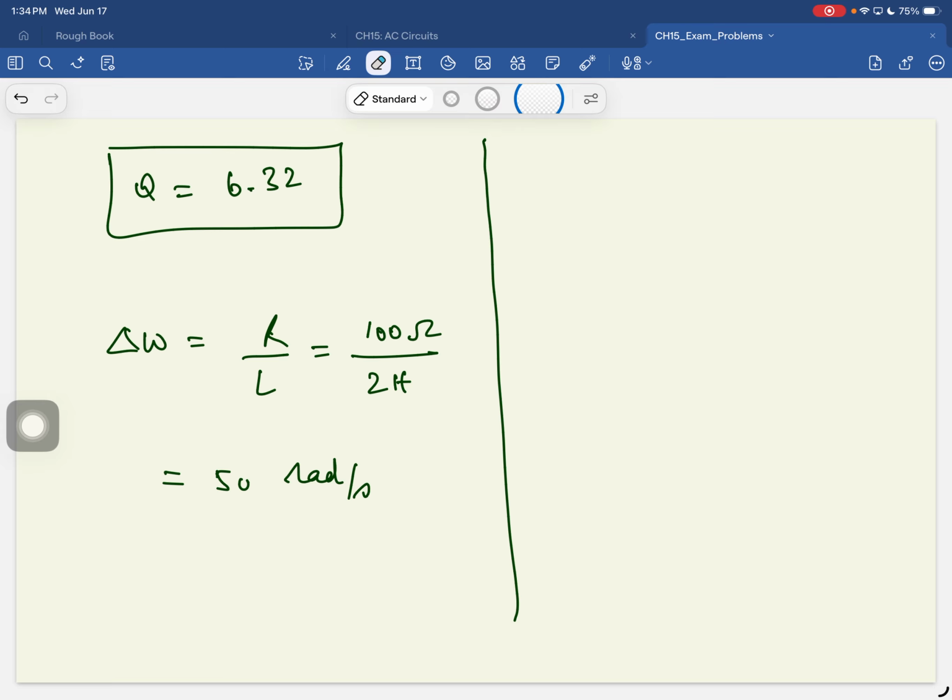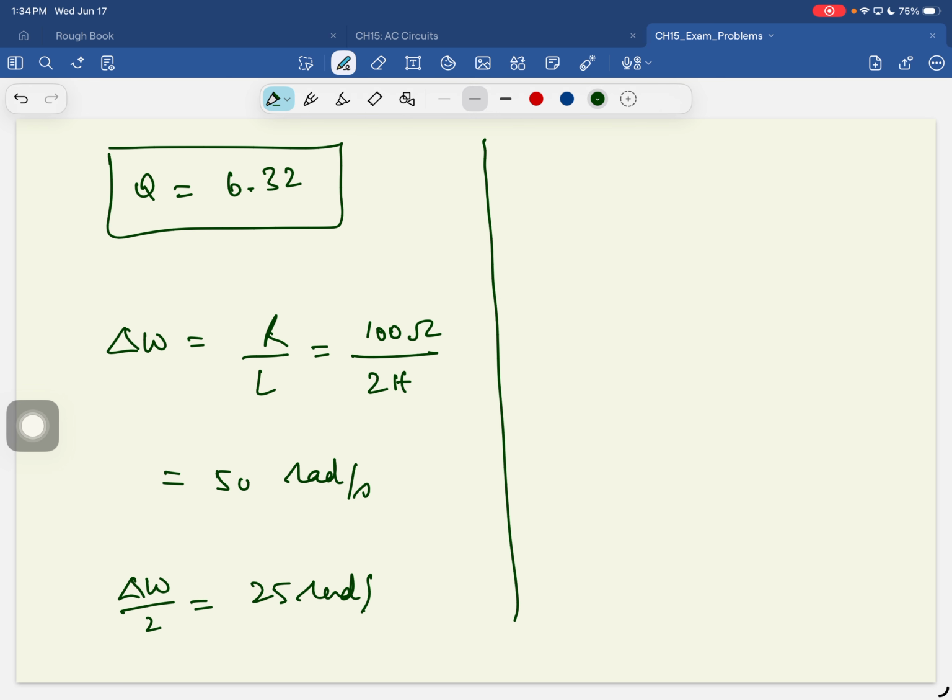Okay, so current went down from 13.6 amps to 0.75 amps. And voltage went up from 110 volts to 2000 volts. So this step-up transformer steps up the voltage and steps down the current.